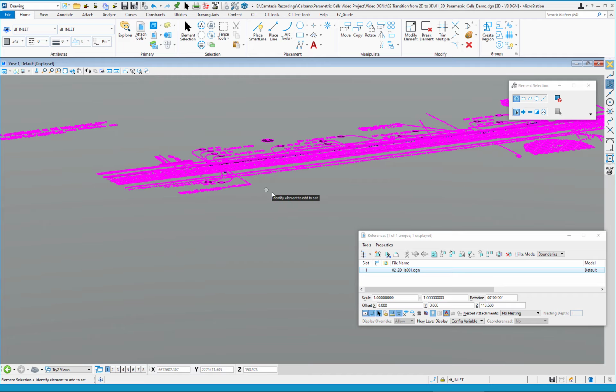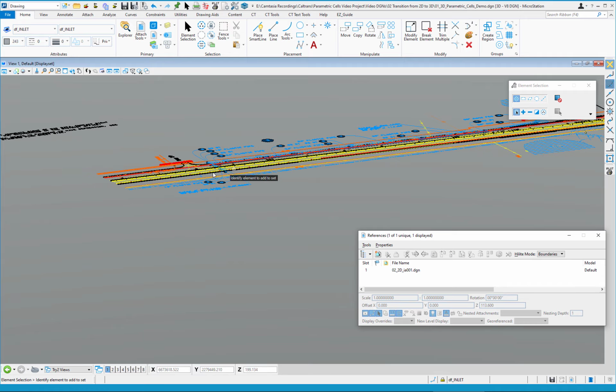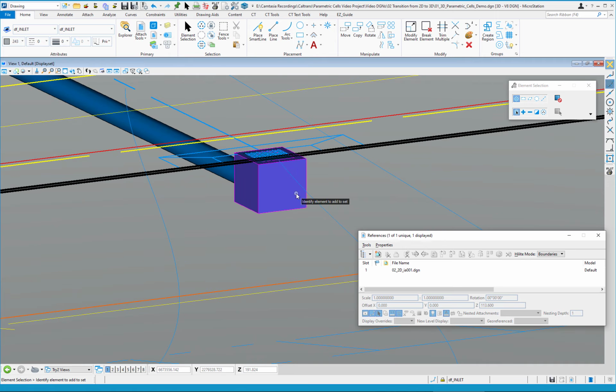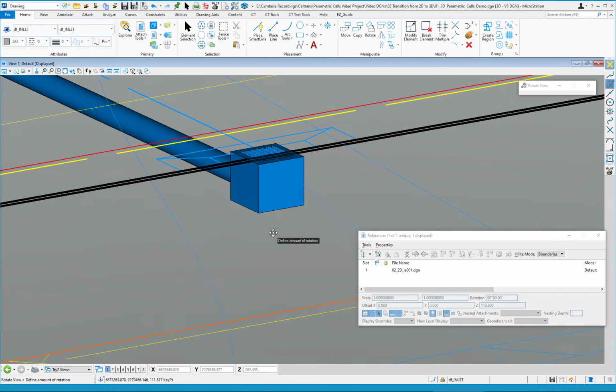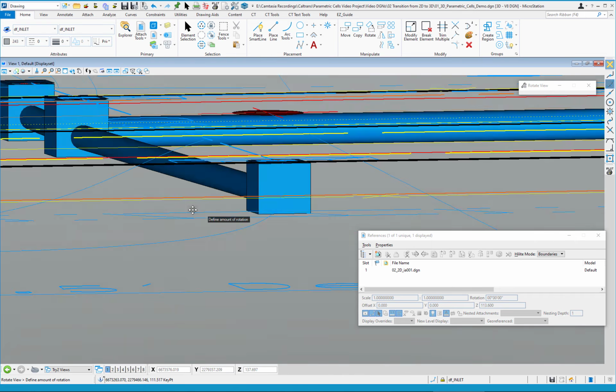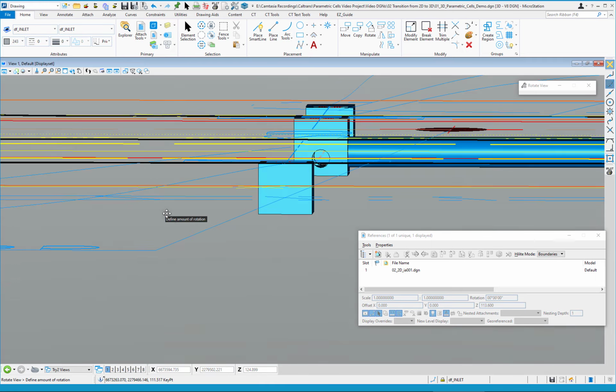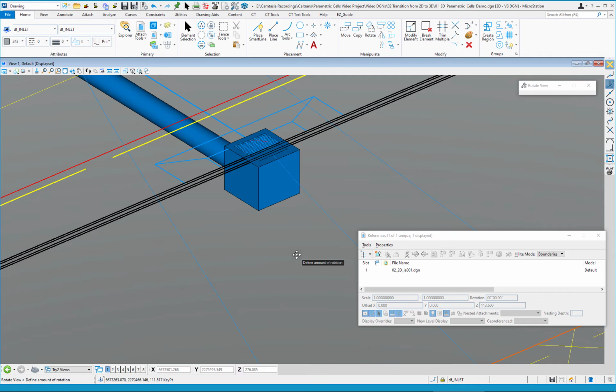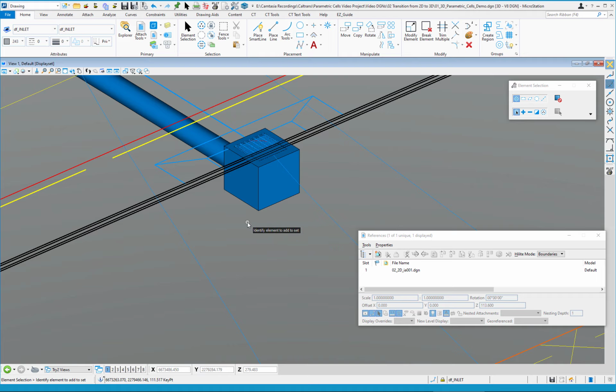And then you can see, I'll go ahead and unselect my reference file. If I zoom in over here and rotate my view, you can see my layout sheet is now at that same elevation as the top of the DI. So that's a way for you to move the reference file to a different elevation. You could move it horizontally if you needed to, but it probably shouldn't be because it should be horizontally correct coordinate-wise. It's just the Z elevation that needs to be adjusted.